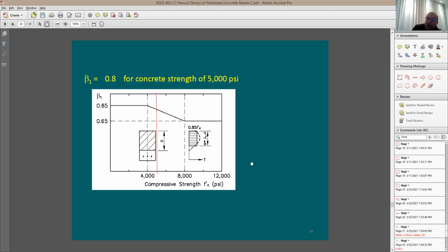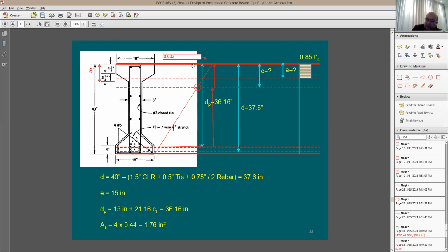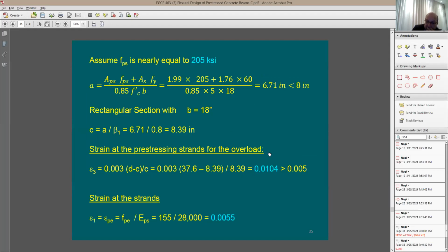is going to be right when the depth of the neutral axis is at this point, which means it's going to be at the ultimate point, the capacity point. And this c depth is going to be based on the same value. So we're looking at the capacity point. The strain in the steel at the capacity point equals 0.01. But the steel here, the actual strain, when you put this force to it, you're at 0.05.